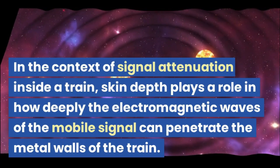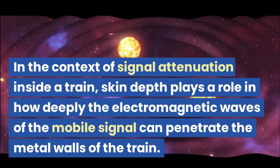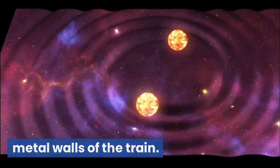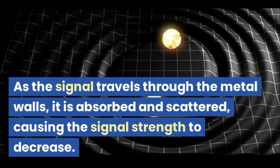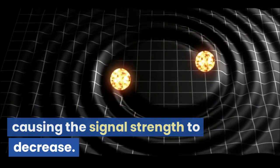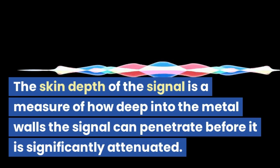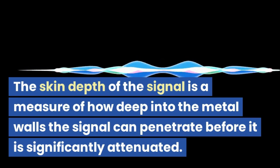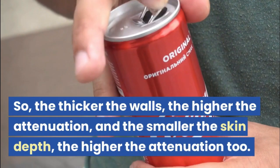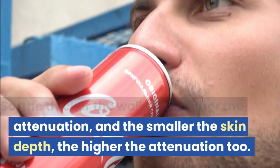In the context of signal attenuation inside a train, skin depth plays a role in how deeply the electromagnetic waves of the mobile signal can penetrate the metal walls of the train. As the signal travels through the metal walls, it is absorbed and scattered, causing the signal strength to decrease. The skin depth of the signal is a measure of how deep into the metal walls the signal can penetrate before it is significantly attenuated. So, the thicker the walls, the higher the attenuation, and the smaller the skin depth, the higher the attenuation too.